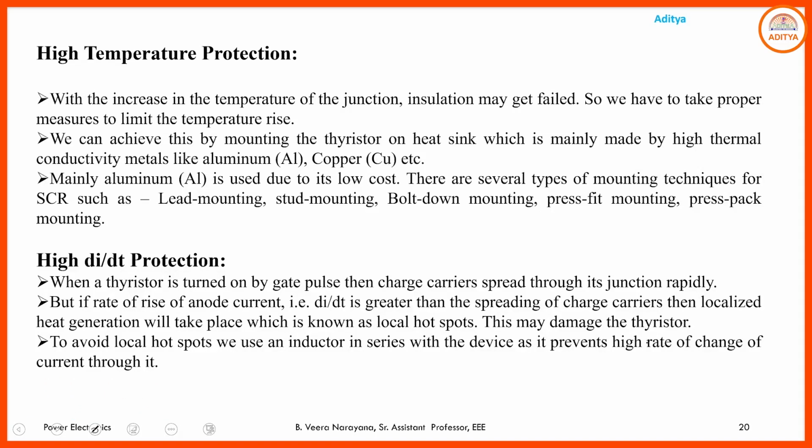So temperature protection should be achieved by mounting the thyristor on heat sinks, which are mainly made of high thermal conductivity materials like aluminum or copper. Mainly aluminum is used due to its low cost. There are several types of mounting techniques for SCR such as lead mounting, stud mounting, bolt down mounting, press fit mounting, press pack mounting.